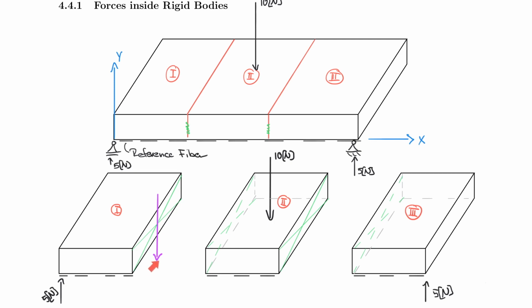But now we have this imbalance, or we can potentially use this force to bring the system in the vertical direction in balance. But the trained engineering eye already sees that these forces, even if they have the same value, 5 Newton and 5 Newton, they would cause this system or this rigid body or the part of the body to rotate. In this case, it would rotate clockwise. So we need to do something against that. We need to bring in a force or some system that prevents rotation. And of course, you already know how that works.